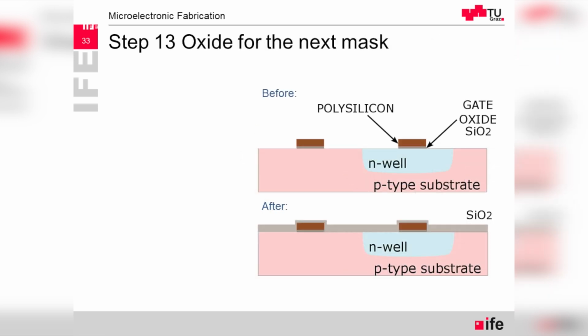And the next two steps will be, again, ion implantation in order to add the drain, source and bulk, two different types. So we have to do this again in two steps. What is peculiar is that we have done first the implantation of N-well, and we didn't do then the P+ doping for the bulk contact of NMOS and the drain source contact of PMOS and the respective N+ complementary, but we have gate first. It's not by a mistake. Do you know what is the advantage of doing this?